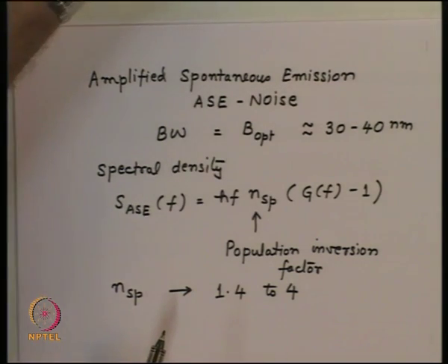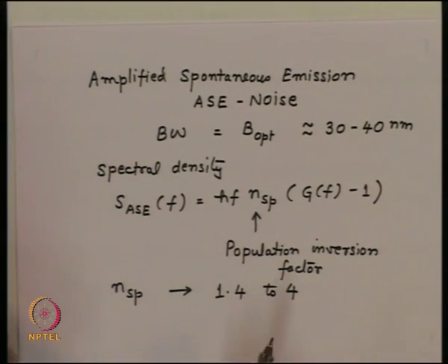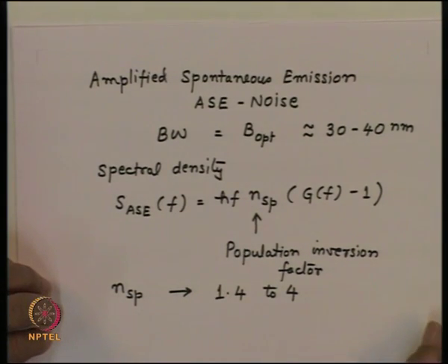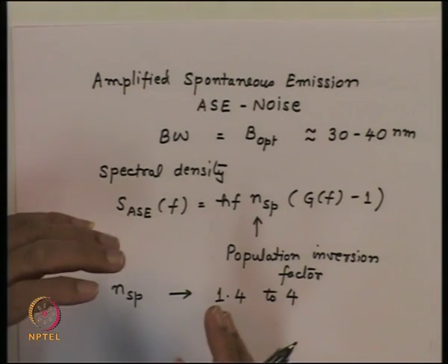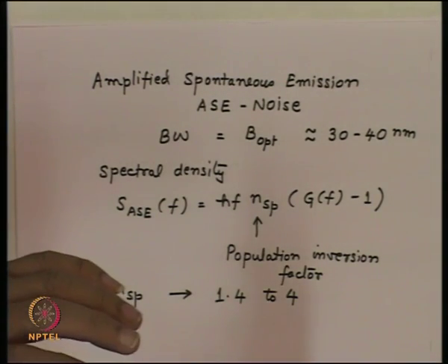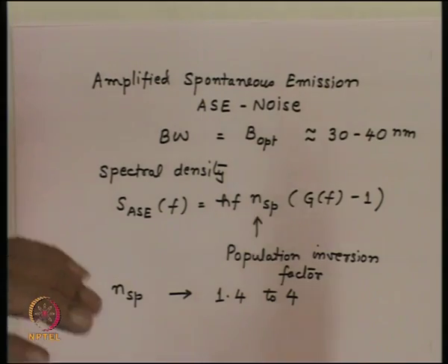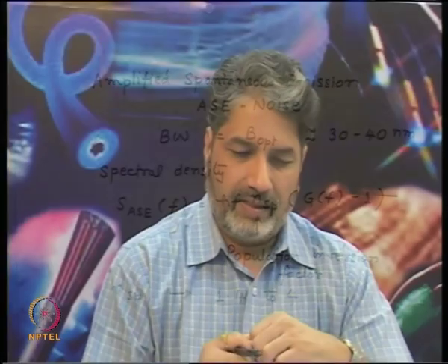So essentially then one can get the amplified spontaneous emission noise or ASE noise, and this also depends upon which way the amplifier is pumped. In fact, we talk about two different schemes, co-propagating and counter-propagating, because the ASE contribution is different in the two cases, and this is what essentially is shown here.